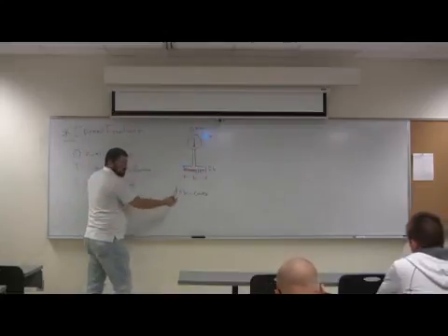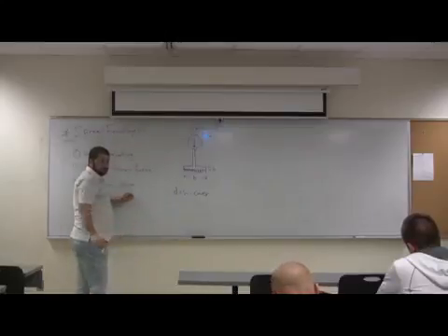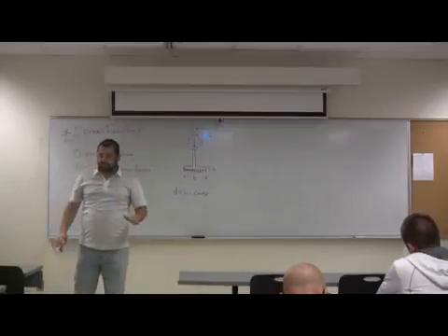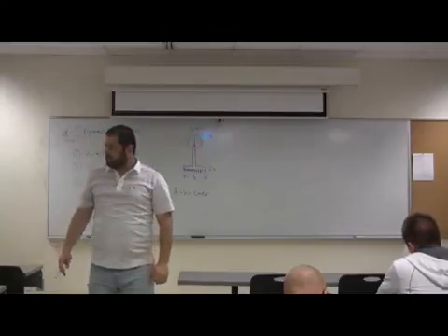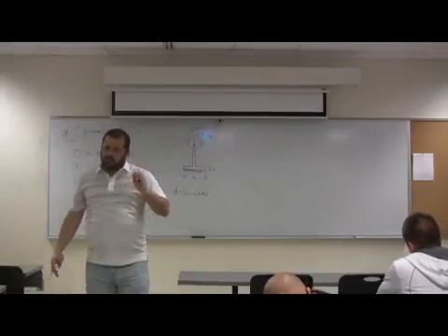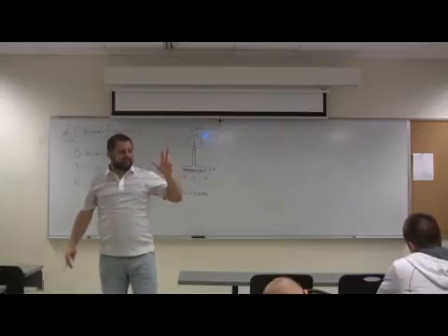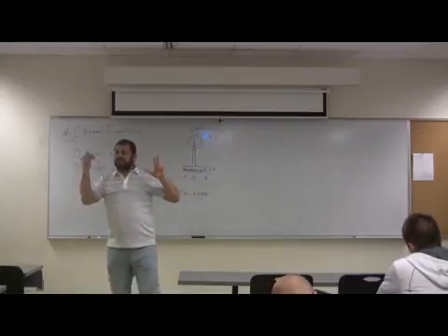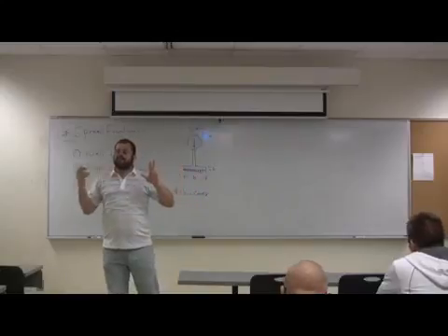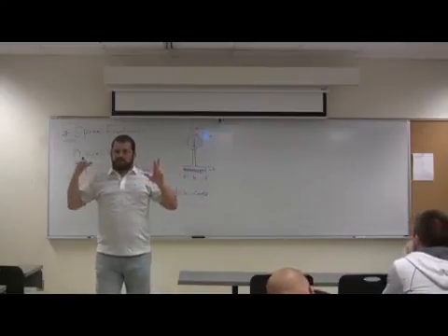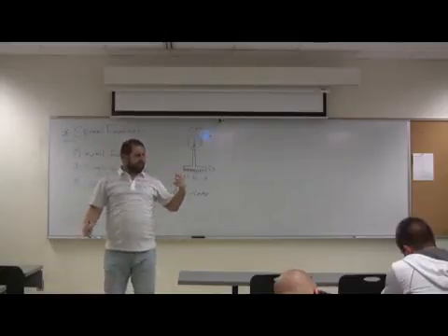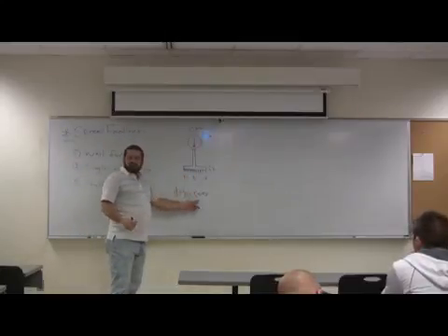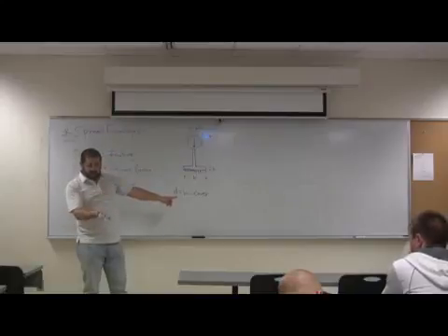So how much is the cover according to the ACI code? Clear cover over the reinforcement of 3-inch minimum. The ACI calls for a clear cover of 3-inch. That's the clear cover, so the cover to the center is usually 4 to 4.5 inch. You can take it 4 inch if you want. So d will be H minus the cover. The clear cover required over the last part, the closest part to the soil, is 3 inch.